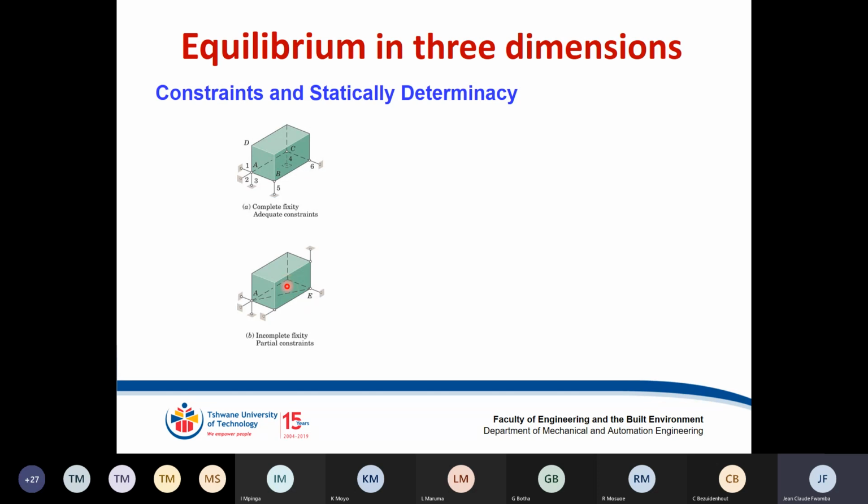I'm not sure. If you check that corner, where your 3 axes meet at your 0 point, if I should call it that way, it's open, it's unsupported, which might create motion in the z-axis, which becomes a problem, right? So having such a setup, your system is regarded as partially constrained, meaning there is a possibility of motion, in this case, in your z-axis, right? The next one, z-axis, I've got 3, good.